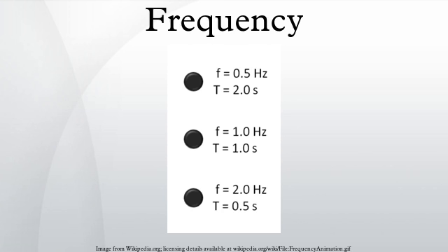Frequency counters can currently cover the range up to about 100 GHz. This represents the limit of direct counting methods. Frequencies above this must be measured by indirect methods. Heterodyne methods, above the range of frequency counters: frequencies of electromagnetic signals are often measured indirectly by means of heterodyning. A reference signal of a known frequency near the unknown frequency is mixed with the unknown frequency in a nonlinear mixing device such as a diode. This creates a heterodyne or beat signal at the difference between the two frequencies.